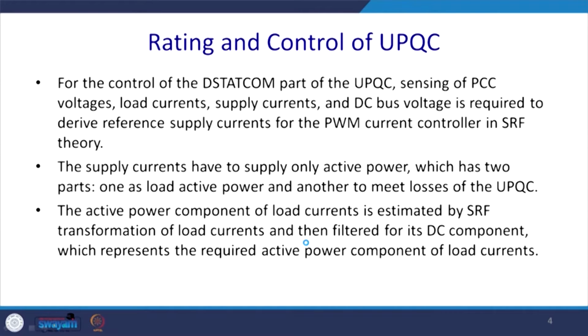So, thus what we can say for the control of the DStatCom part of the UPQC, the sensing of UPQC voltage, load current, supply current and the DC bus voltage is required to derive the reference current of the PWM control by SRF or instantaneous reactive power theory or other techniques which have already been mentioned.